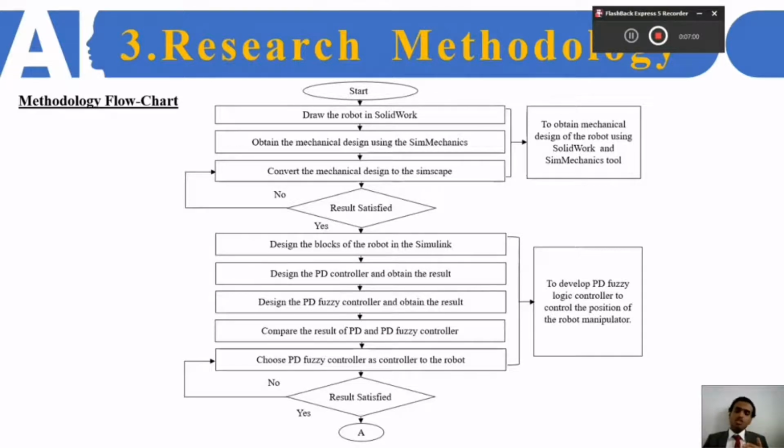The second objective is to develop a PD fuzzy logic controller to control the position of the robot manipulator. What I did is design the blocks of the robot in Simulink, after I did it from SimMechanics, the previous step. After that, I designed the PD controller with a unit step function, and then I got the output of the PD controller.